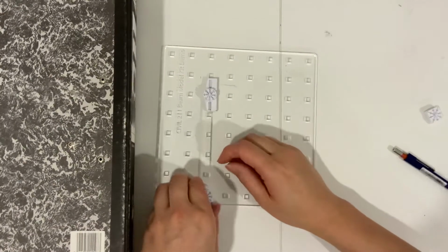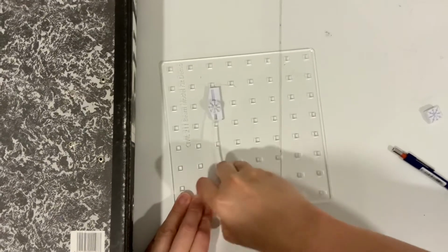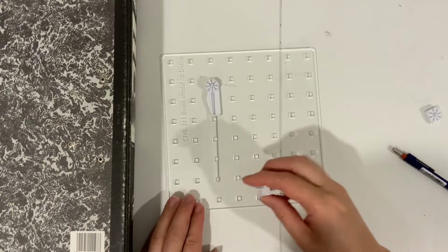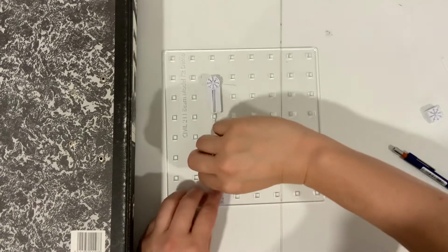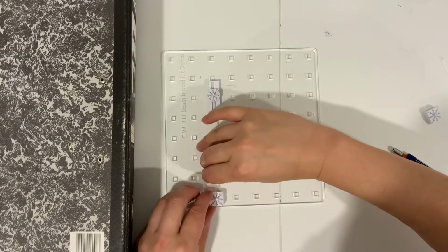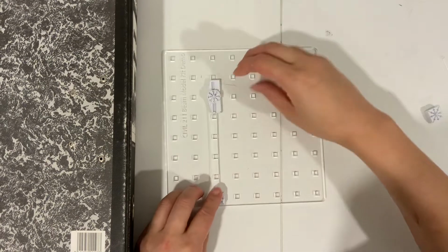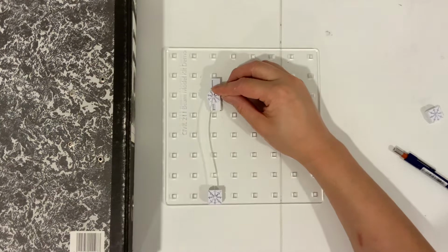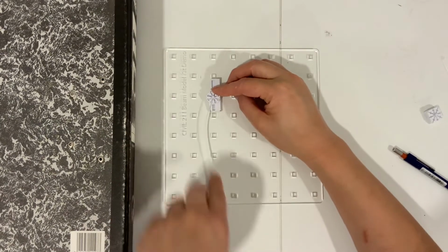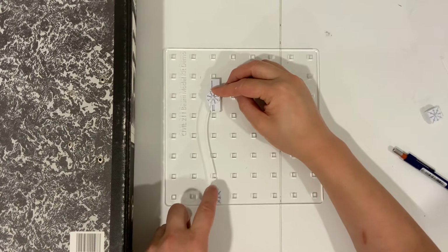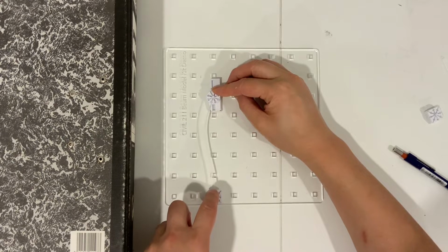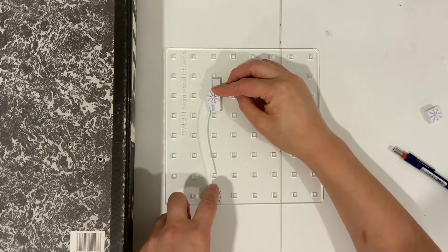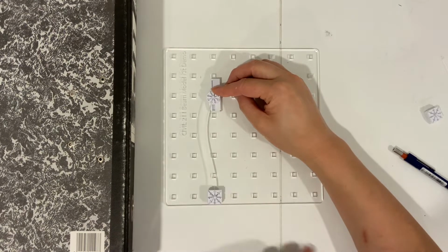Now if I change this from a pin, so at the bottom of a multi-story building you might have a fixed column base, and if I did that, you can see it's a different shape. This one here used to be, when it was a pin, rotating around, and you can see that now it is coming out at 90 degrees.